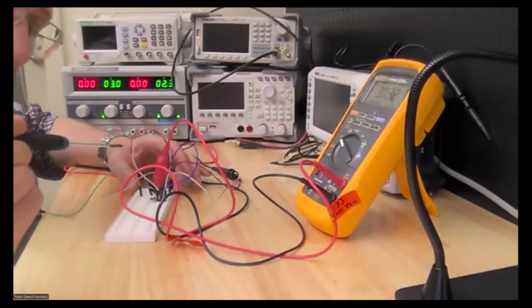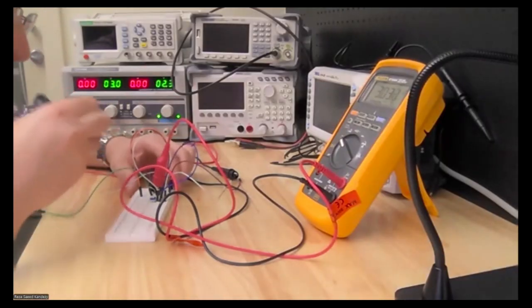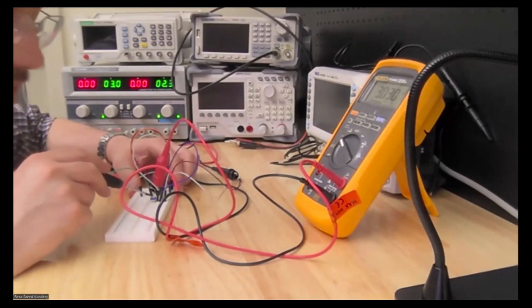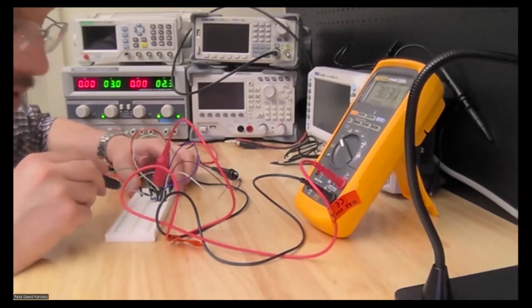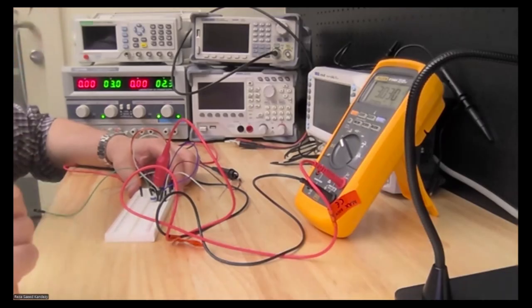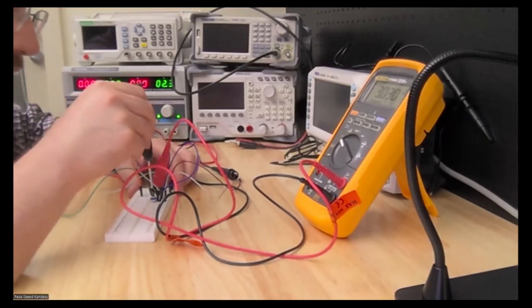Now, we know that the current in a collector is, ideally, a function of the current in a base. So no matter what type of resistance is here, that current would not change. So what would change this resistance? The voltage division between the transistor and the potentiometer. So if we change the potentiometer, we're basically changing VCE. Now I am gonna change the potentiometer.